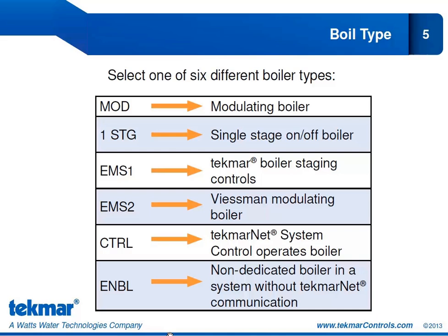What would happen with that is the heat relay would close whenever the mixing device was increasing and reached a position or speed of 10%. Likewise, the heat relay will open when the mixing device is decreasing and reaches a position or speed of 5%. So in this case, the time when the heat relay is closed depends on the position of the mixing device.